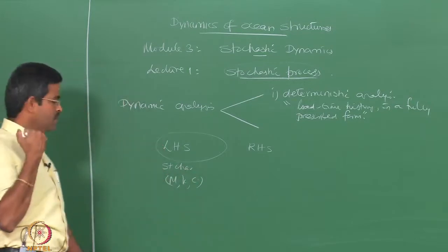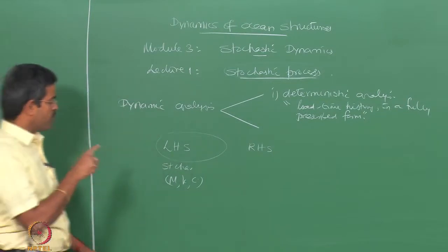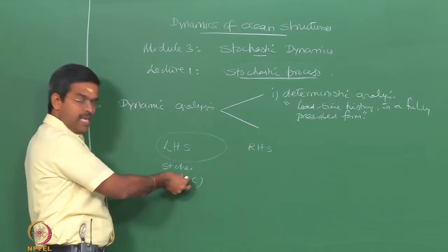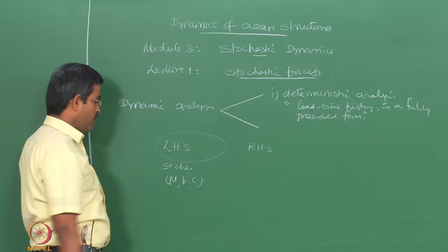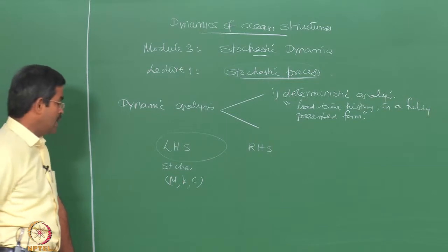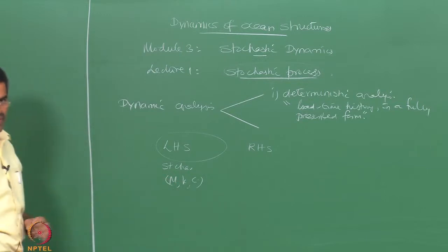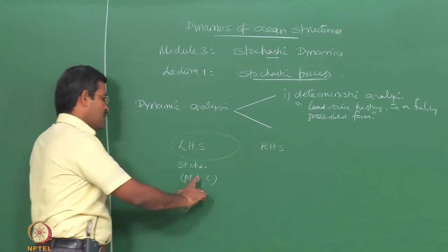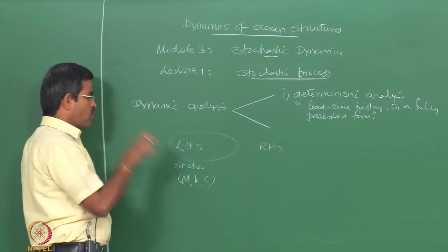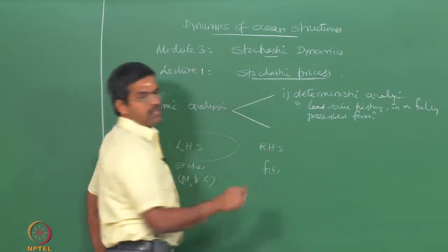Of course, damping is derived from M and K, therefore, obviously damping will also be a functional characteristic of structural properties, maybe not only necessarily material, because K is involved with E, L, A and I. Therefore, material characteristics will also play an important role, but nevertheless K, M essentially are derived from the structural form. Therefore, it is important that they are essentially focused on the structural geometry, whereas if you look at the right hand side of the equation of motion, essentially this talks about loading characteristic.